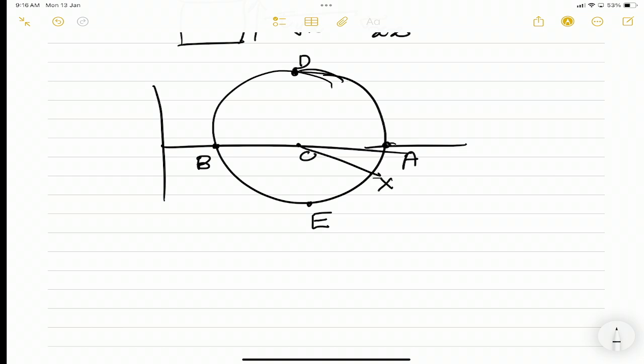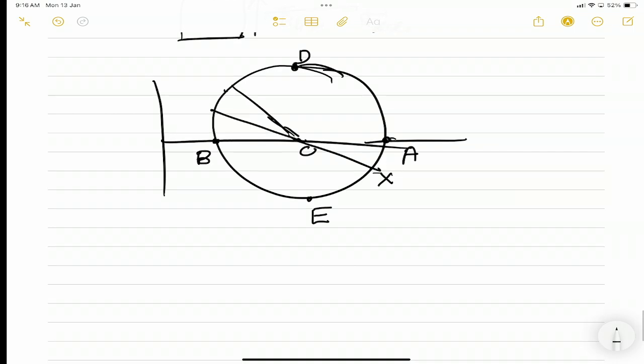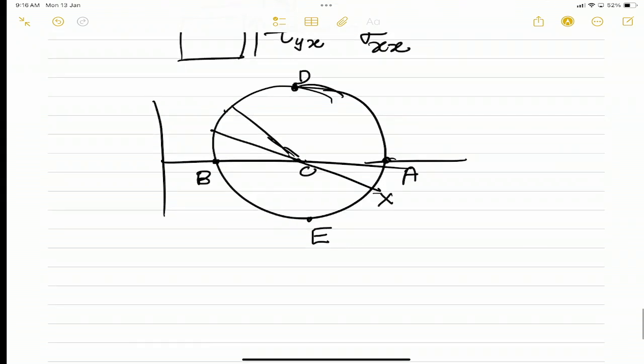This was our original X, and this was our original Y. So original stress was at X and Y, these were the original points. A and B we have already seen, the points of principal stresses.